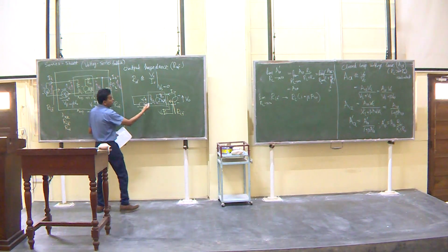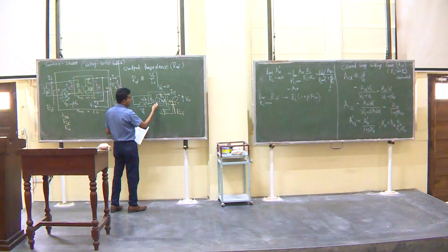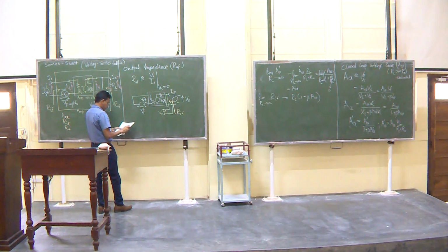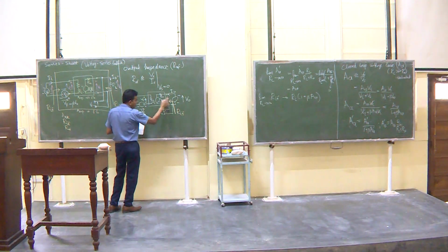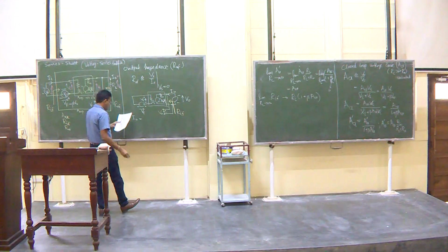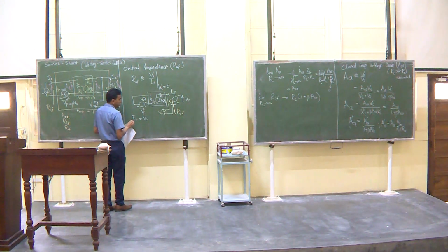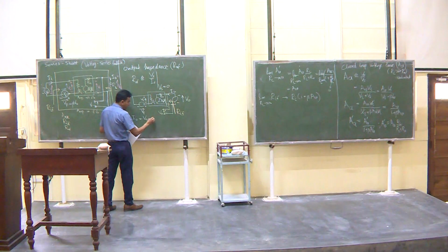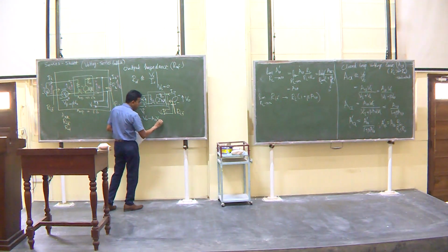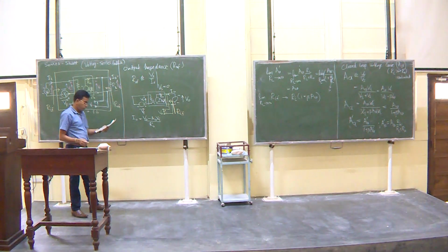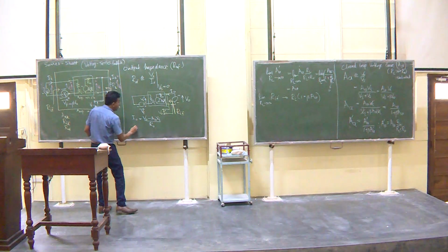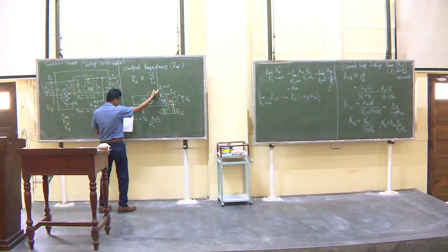So I out is basically, I can write the expression for I out is equal to this voltage applied across this. So that is this voltage difference divided by R naught, right. So V out, the applied voltage from the external source, minus AV times Vi, divided by R out, and Vs, the other source, is now 0.